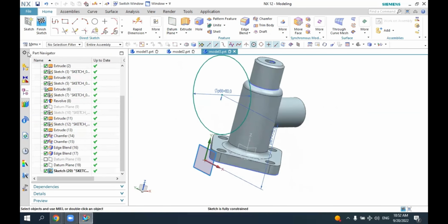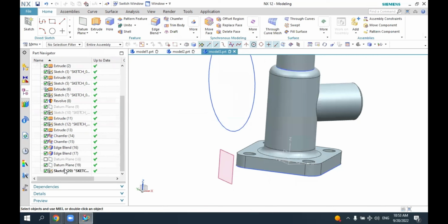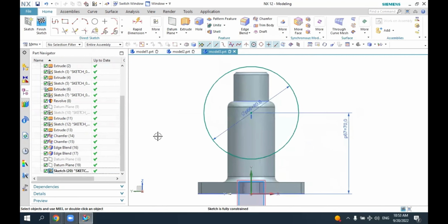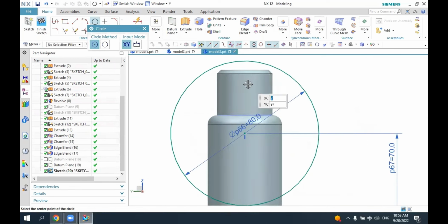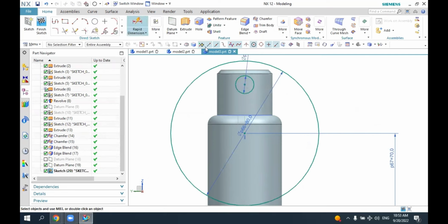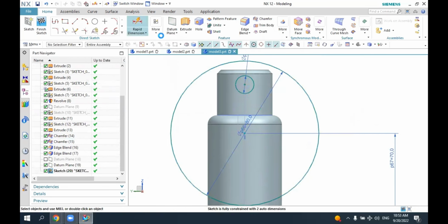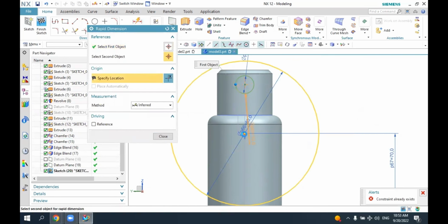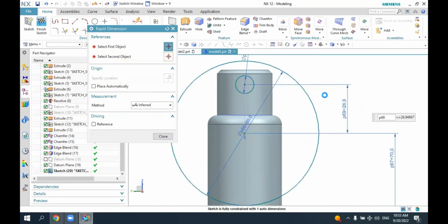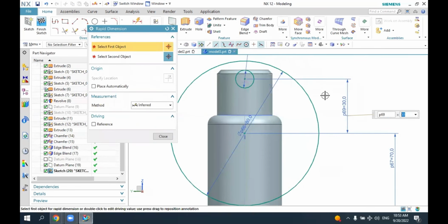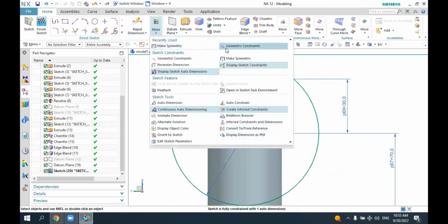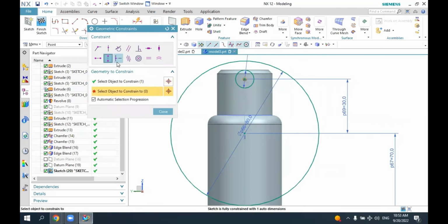Now let's finish, and let's double click on this one. Let's create the circles again directly on this sketch, the circle with the 10 millimeter, and let's define the distance from this center to this center. Sorry, copy dimension. Distance from here, the center of this one is the 30 millimeter. So geometric constraint, vertical. Here the vertical is selected with this one, so it's vertically located.